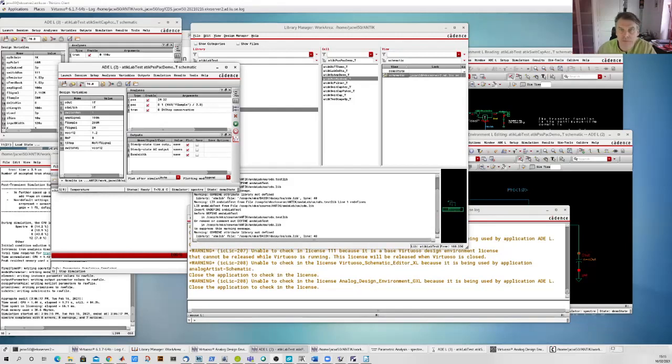So for simulating a square wave, to get an accurate result, we will typically need a very wide bandwidth of our simulator to capture it. Otherwise, we will get artifacts in our simulation. But for sinusoids, it's pretty useful. That's the message, because we have a narrow frequency, so it's easy for the simulator to find this steady state behavior.